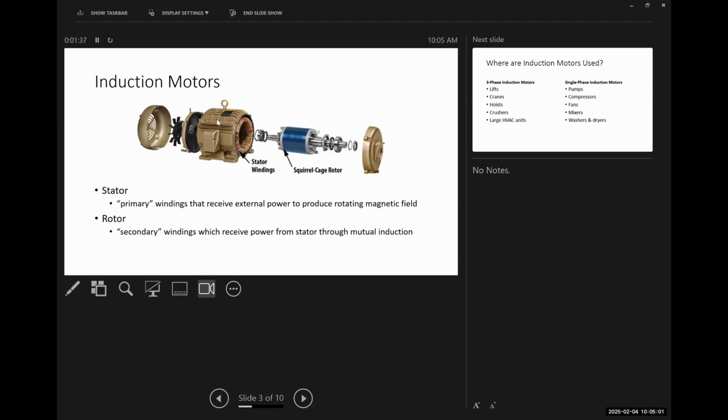Well, I guess there's an arrow that says stator winding. So our stator is literally just a big electromagnet, okay? That's just a whole bunch of windings. It's typically a three-phase winding. And it is stationary, so it's just housed inside this very large, usually cast iron casing, which is actually going to become part of the magnetic circuit as well.